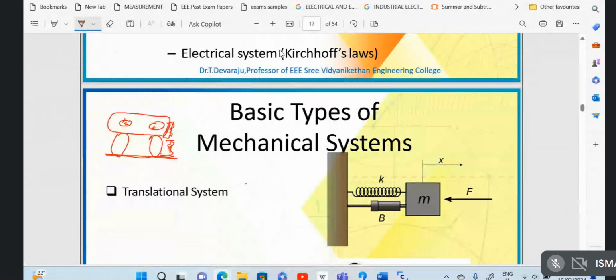The springs are meant to give it comfort from vibration so that you don't have a shock. The spring is supposed to do its own work to follow the vibration itself. But the shock absorber will tend to control the vibration of the spring and bring it to rest.